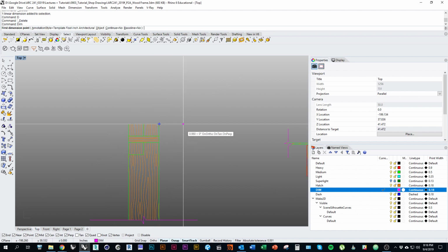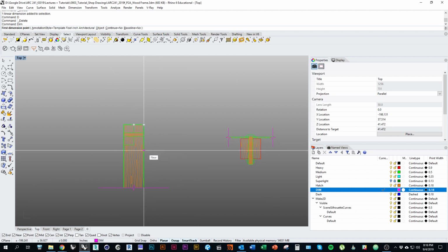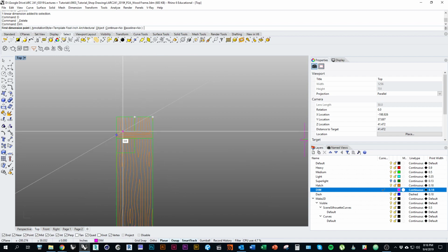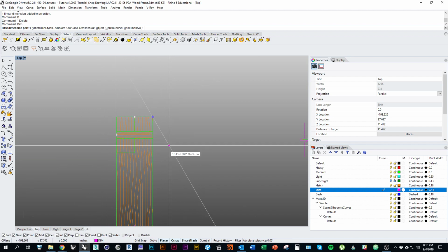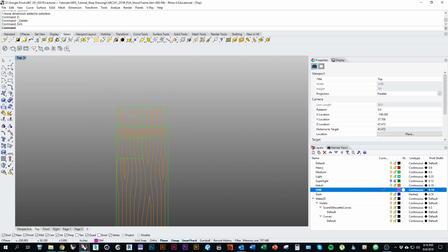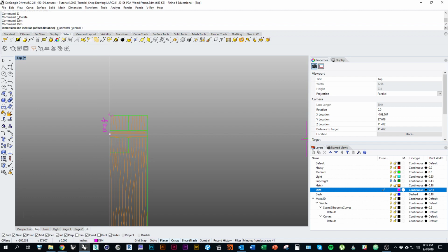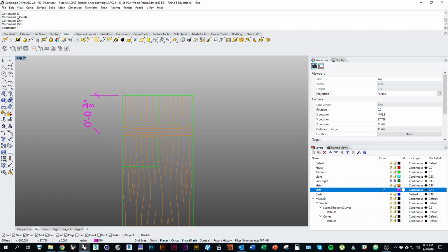What we really want to show with the details is how thick different parts are, and where the critical parts of the joints are located. So the most important thing with this detail is to locate where that pin is going to go. We want the pin where we drew it, right in the middle of the thickness of the material. The way we would measure that is by measuring from the outside edge to the center of the pin. So with joints and structural elements like that, you're usually performing measurements from an edge to a center, or from a center to a center.